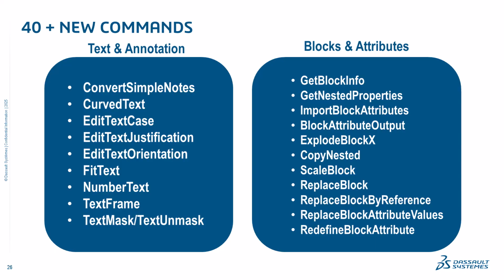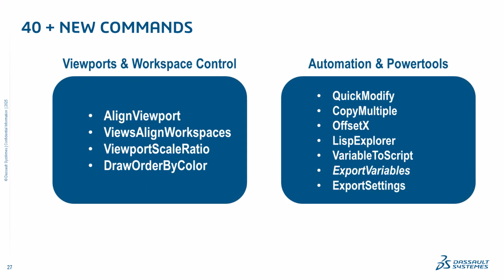On the block and geometry side, we now have commands like Get Block Info, Explode Block X, Scale Block, and many more. Continuing with the additional commands, you will also see capabilities such as Align Viewport and Viewport Scale Ratio, which provide greater control when working with layouts and viewports.